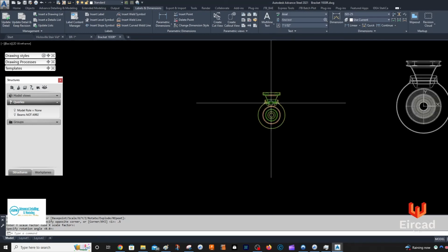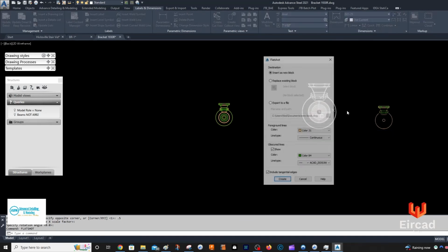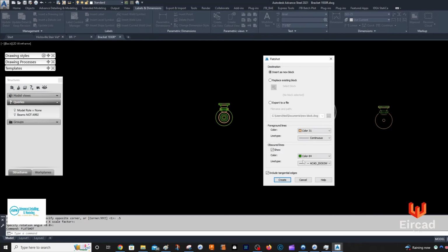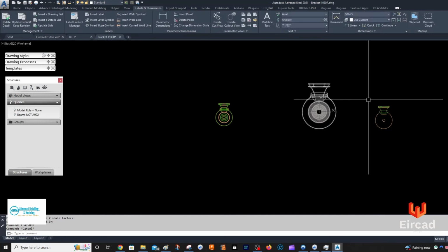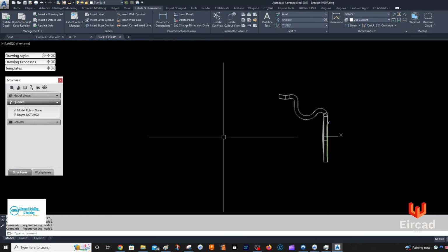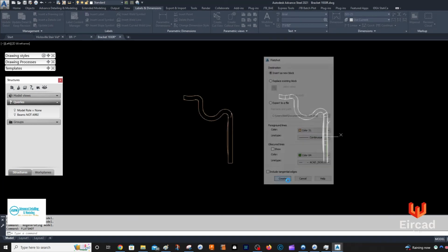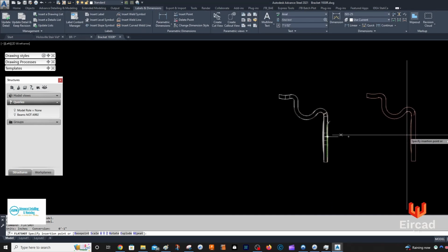And then of course you can do the last one, which would be to repeat the command again. So obviously if you want to do one the other way, you have to rotate the UCS and then look in this way. And we don't have to rotate it, I don't think, but it's probably better to be in 2D kind of. And then do Flatshot again. And I don't want to show the obscured lines or the tangential lines. Create, and it'll give you that view from the side.